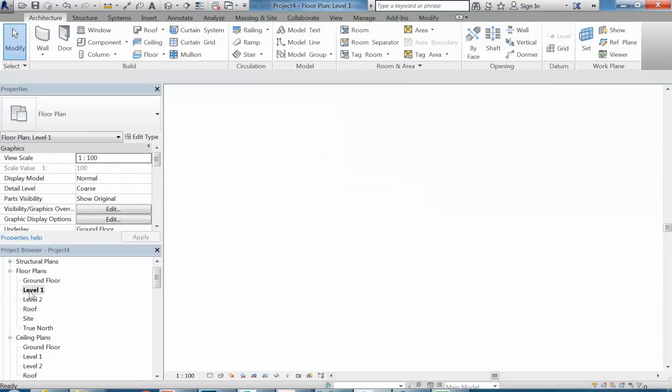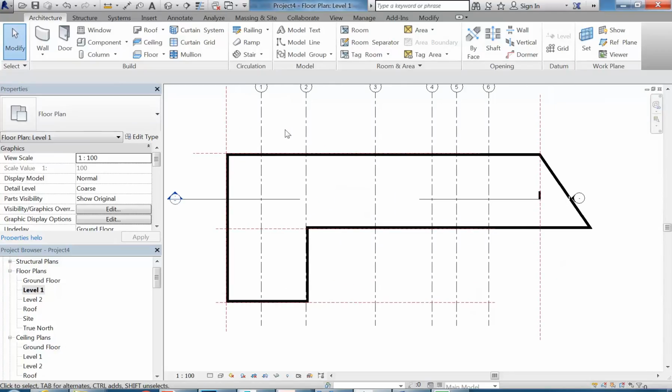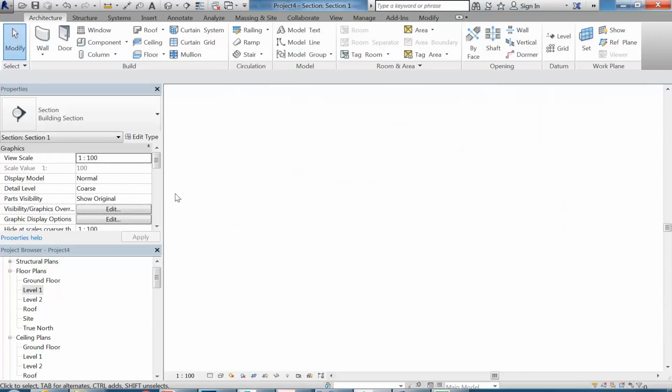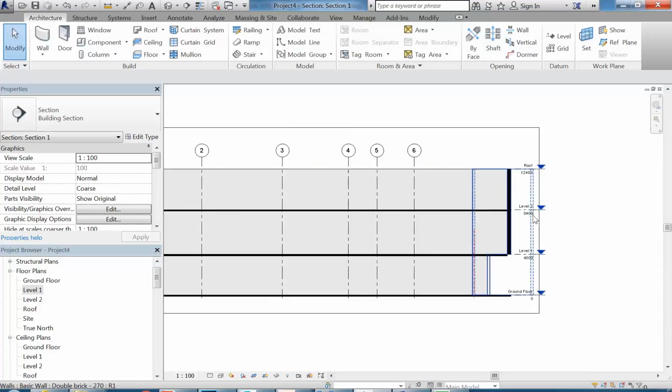This is a common issue people have when you're first setting up your projects. Have you ever had that situation where the ceilings aren't visible in your ceiling plans and it won't let you place lights? And the reason usually is the way the levels have been done. So if you put too many levels in at the beginning, particularly if you put a level in for a ceiling, then you'll get that problem.